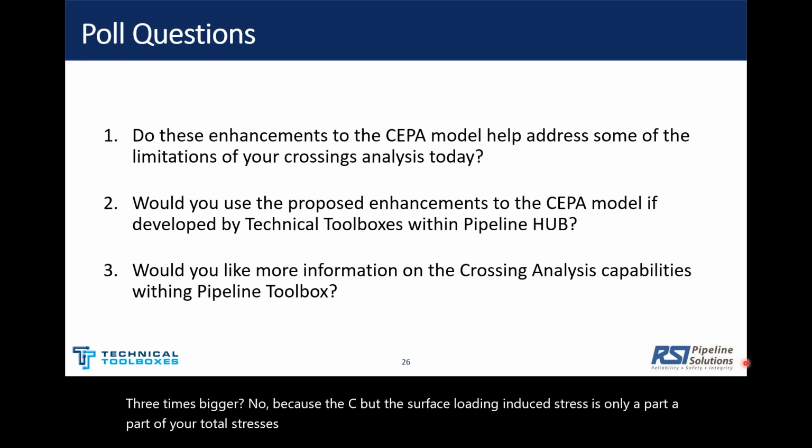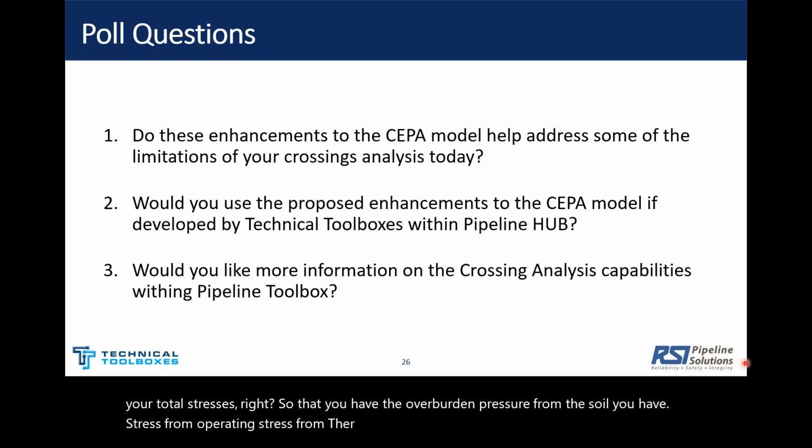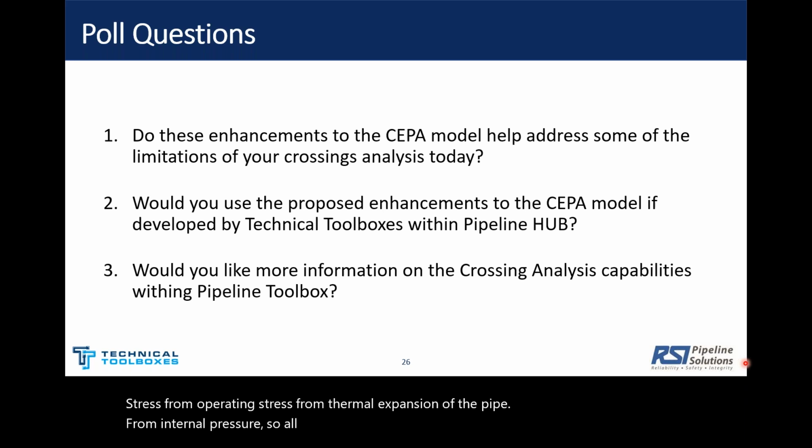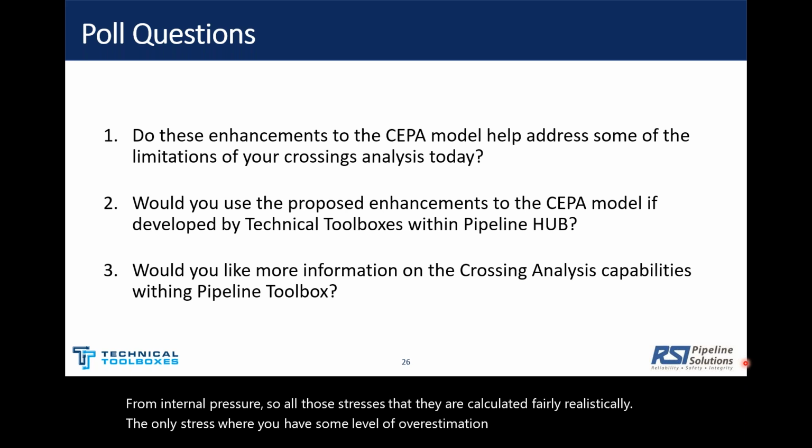So you have the overburden pressure from the soil, you have operating stress, stress from thermal expansion of the pipe, and from internal pressure. All those stresses are calculated fairly realistically. The only stress where you have some level of overestimation is the live stress.